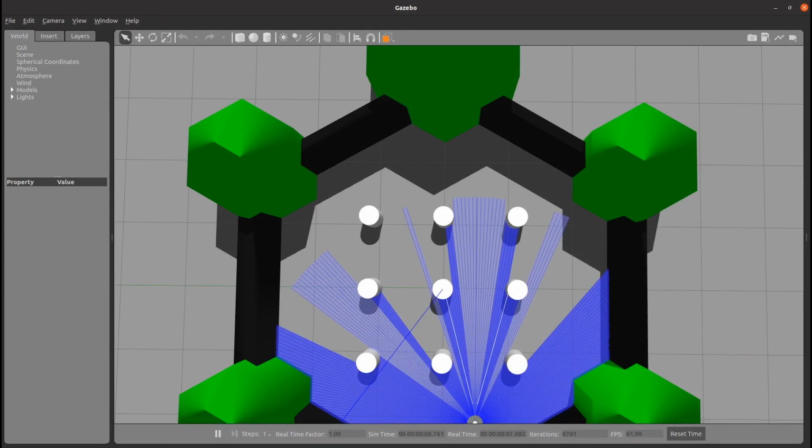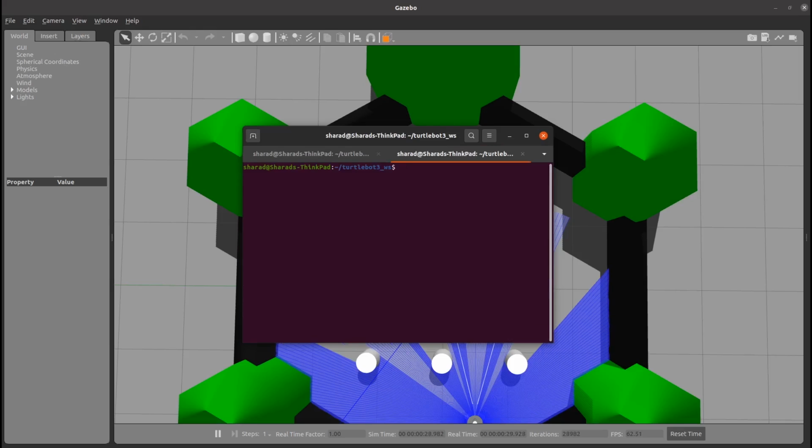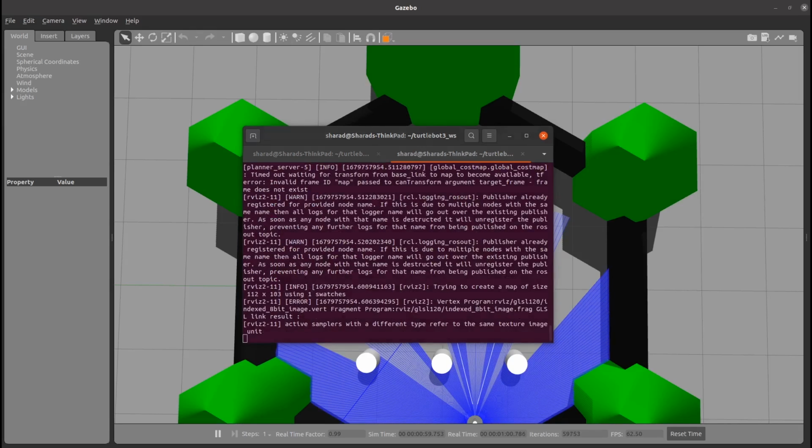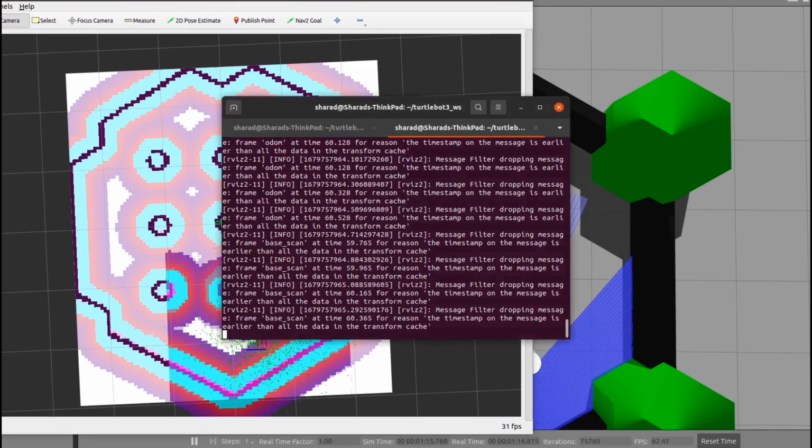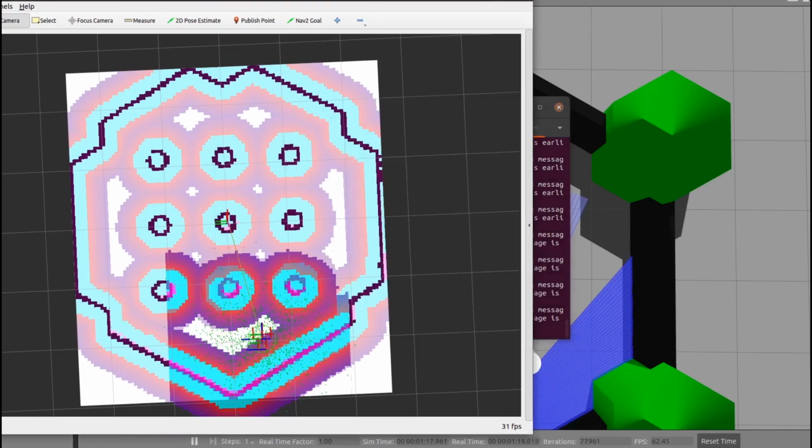What was the second component? As per the previous video, we had our Nav2 infrastructure set up, which was also a part of your TB3 sim. So in a new terminal, source the workspace again. Let's launch your Nav2 infra. So your Nav2 infra with RViz and AMCL initial pose done is also up. The third thing you have to do is launch your autonomy node, which will ask the robot to move to position 1 or location 1, then location 2, 3, and 4.